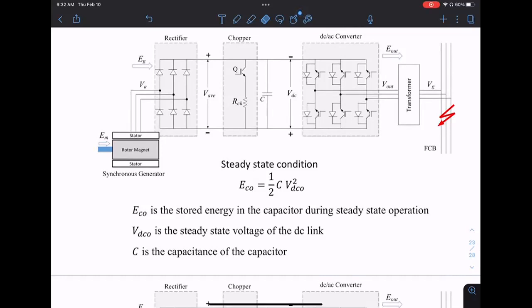This is your average, and you don't want to exceed this value too much during a transient. When you have a design spec, you design the value of this capacitor, the heat tolerance, everything, assuming you'll see this much energy in the capacitor. So you don't want to exceed this number, the steady state energy.